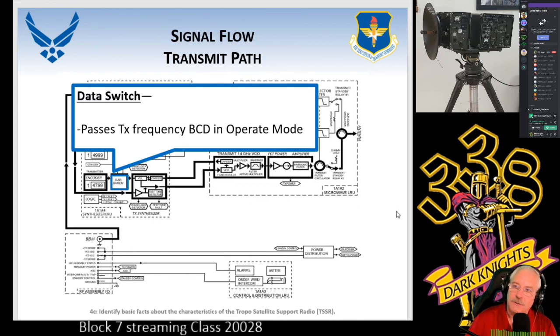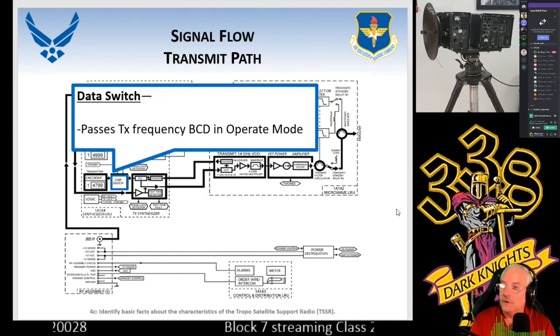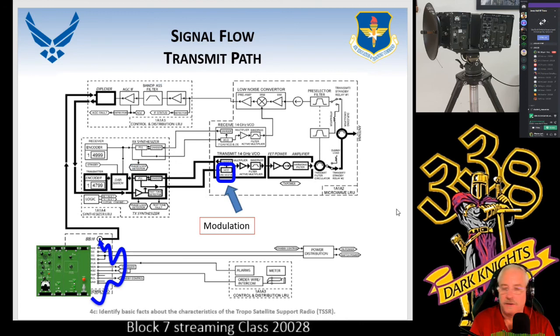So the data switch is the key because we are in operate mode. Everybody remember that switch I talked about on the baseband assembly saying you have standby or operate? Well, operate means that you're transmitting out. Standby means that you're in a loop back but nothing's coming out of the antenna so you can safely work on the equipment. We're going to run that through over to our VCO to tell it what to do.